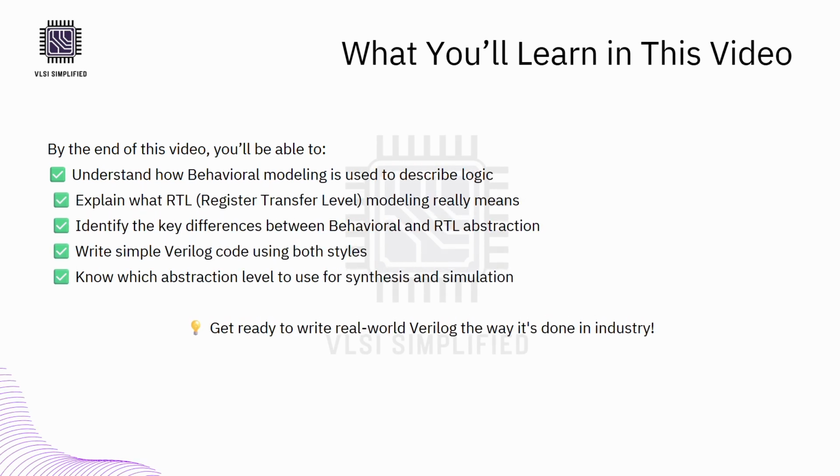Here's what you are going to take away from this video. You will understand how behavioral modeling allows us to describe circuit behavior using high-level constructs like if, case, and loops. Then we will move into RTL modeling, which is what most real-world Verilog designs are based on because it's synthesizable and reflects how data moves in actual hardware. We will compare both behavioral and RTL side by side and show you when to use what.